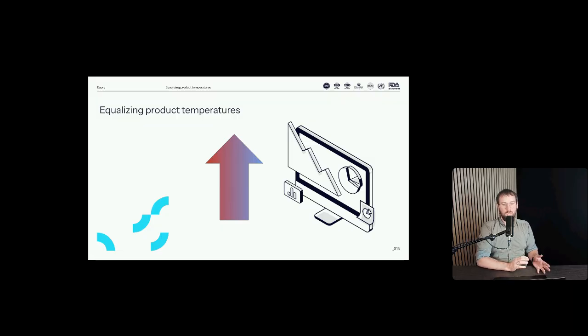A mistake that we often see is that the guidelines will often say you need to perform empty and full studies. That is not entirely accurate. For empty studies, if you have an entirely empty fridge, well, then there are no products in there, so there is nothing to measure on. So basically, it should be called minimal and maximum loading.